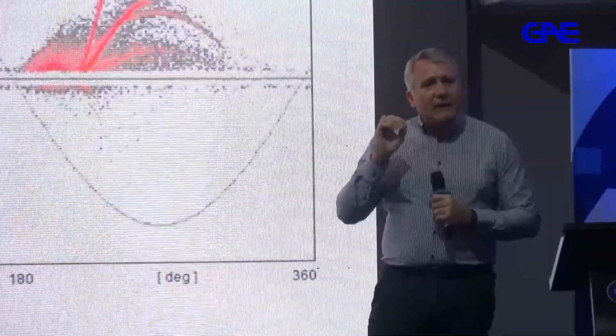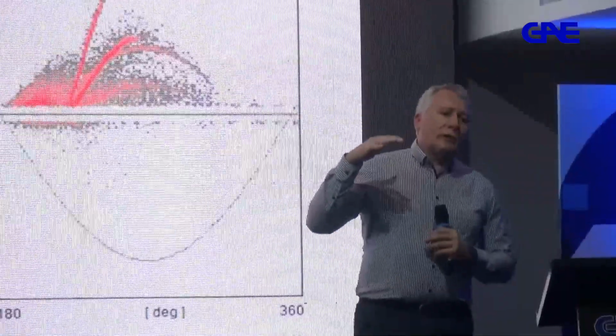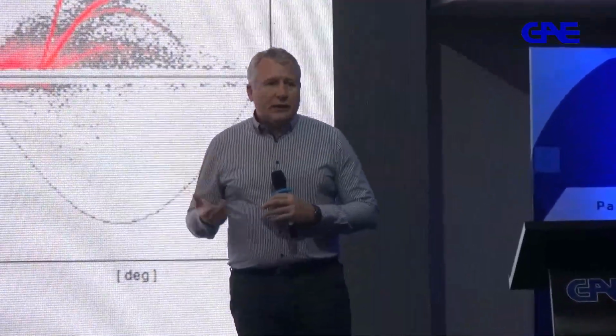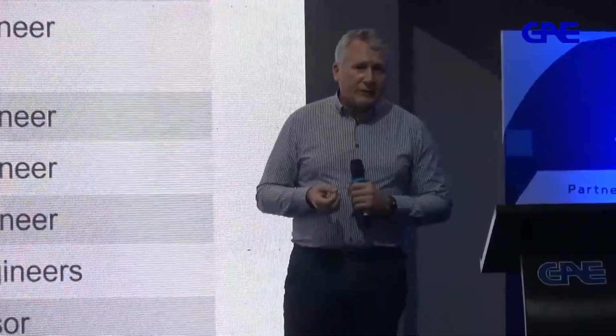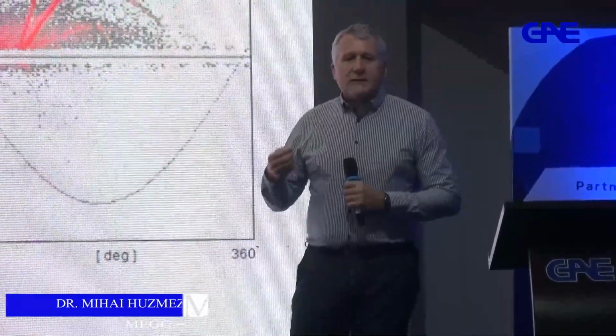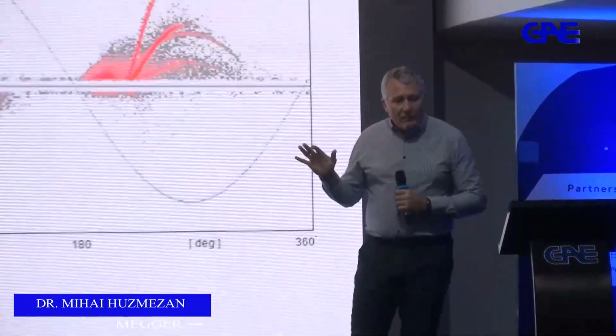So this is a takeaway for all of you: when a certain voltage is being applied, let's say more than 1,000 volts, all insulation materials will experience partial discharge if they are not perfect, and most are not. And then for each fault inside of this insulation material, there is naturally a signature. So that's the takeaway message.